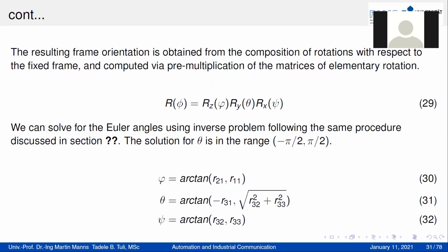Yeah, actually, I think for example, in a plane you have 3 rotations: yaw motion, roll motion, and the pitch motion. The same is true for cars. You have roll, pitch, and the yaw motions. The same is true for robots. We can represent the robots by yaw, roll, and the pitch, which is Euler representation. That's not a problem. But the problem of Euler is, you could have multiple solutions for a simple problem.